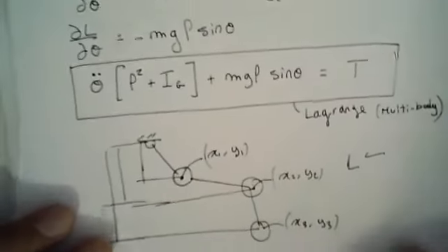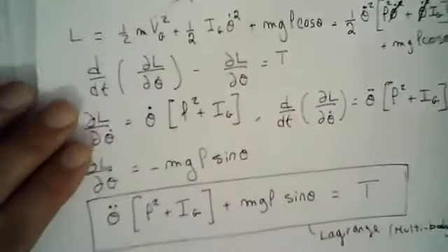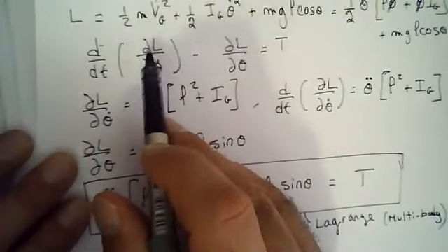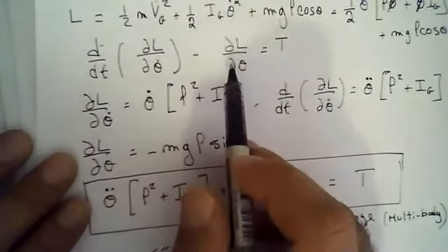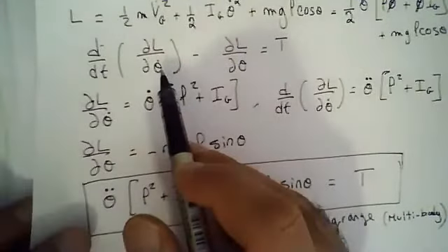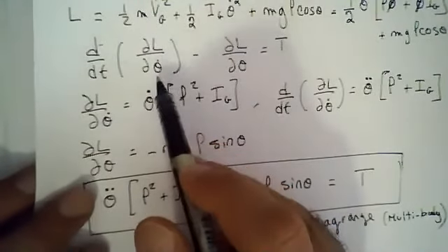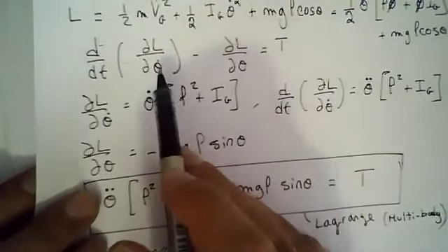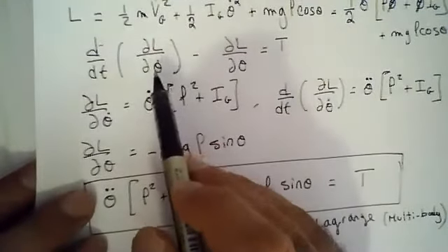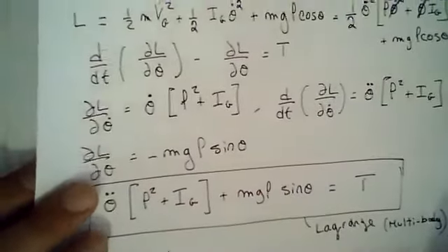What you really end up with when you want to find the equation of motion for theta 2, for example, is that you just change how you are doing the partial derivative of your Lagrange with respect to whatever variable you have. So it's very simple here, right? When you are using Lagrange, it's very simple. The kinetic energy has to be absolute, but other than the kinetic energies, this doesn't have to be absolute here, right? So whatever theta you have, you are good to go here.